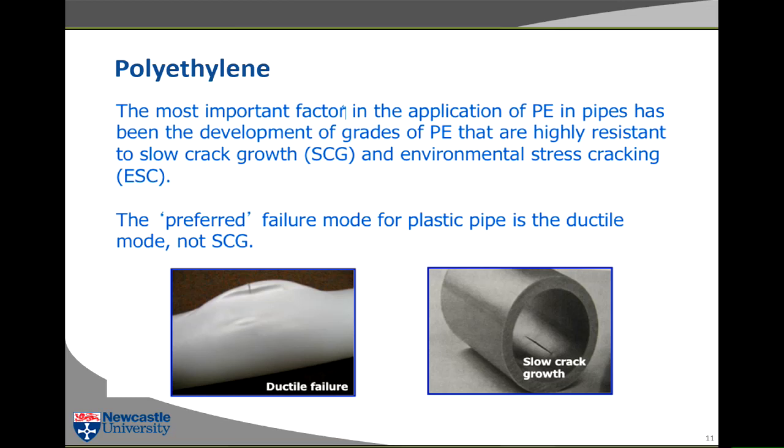So that's what you get, except the same will happen in a metal pipe, except in a metal pipe it will burst there straight away. The metal pipe will bulge and then it will burst in one particular place. A thermoplastic pipe will bulge and it doesn't immediately burst.